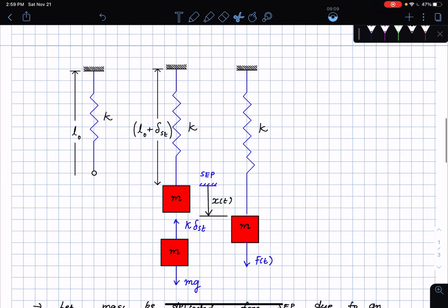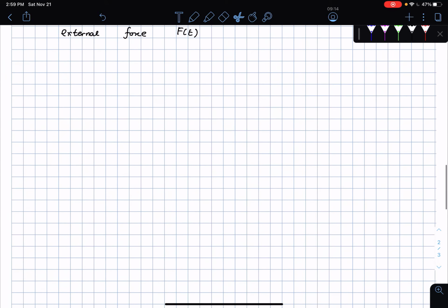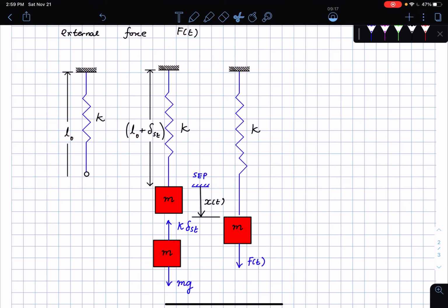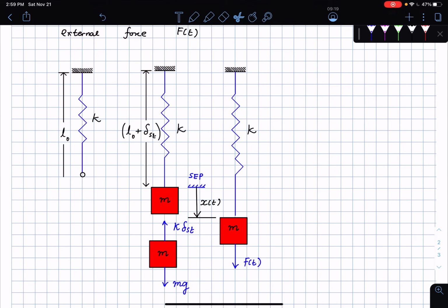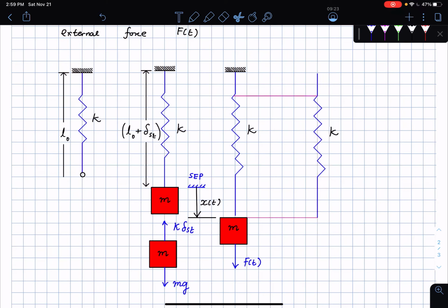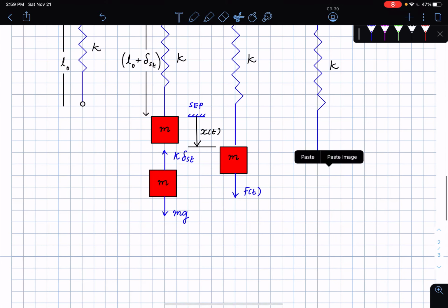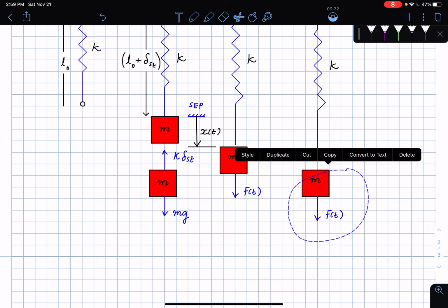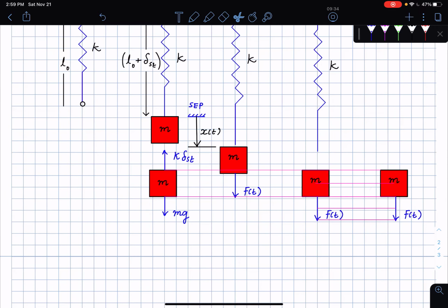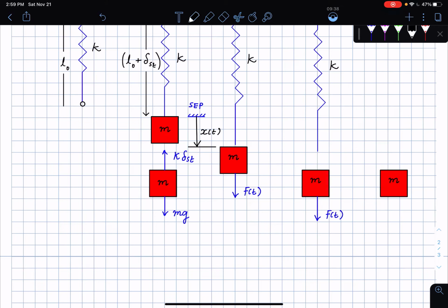Now if I deflect it, I'm going to draw the free body and the kinetic diagrams right underneath and right next to the situation that is shown. Okay, so here is the case. I can draw the free body diagram of the spring and copy that and paste that down here. Okay, then I can draw the kinetic diagram of the mass, and a free body diagram of the mass. Okay, so in the kinetic diagram of the mass, I'm going to have the mass times the acceleration.